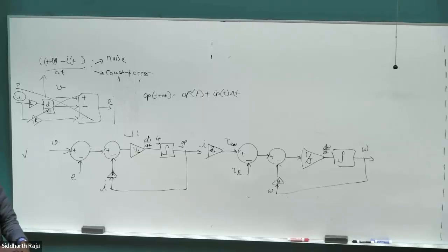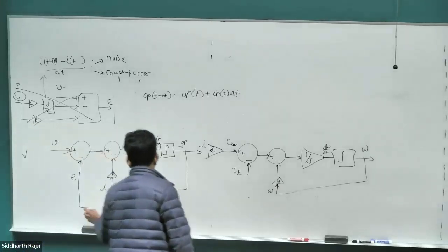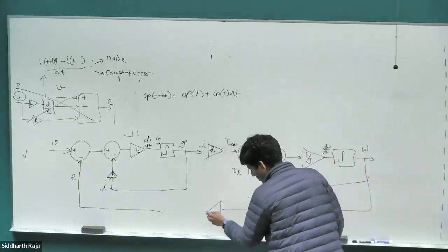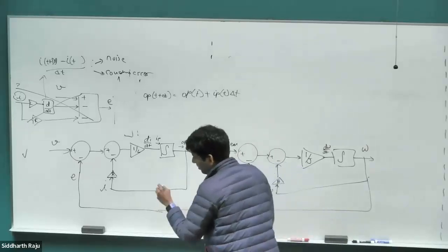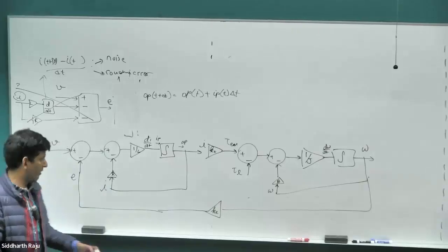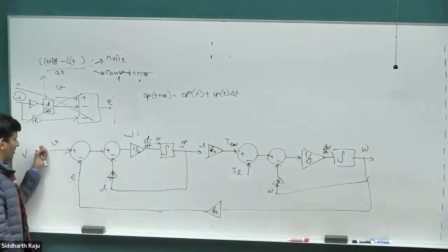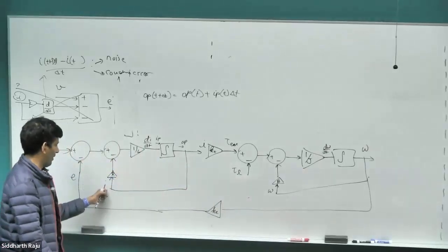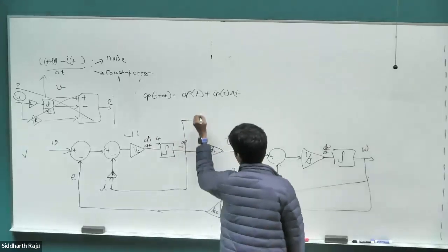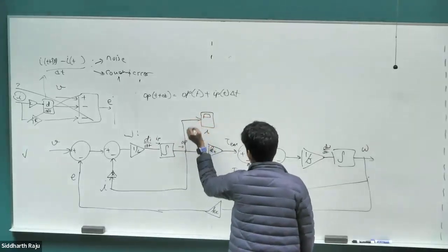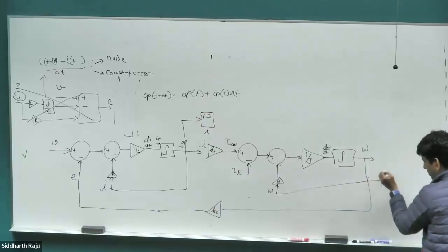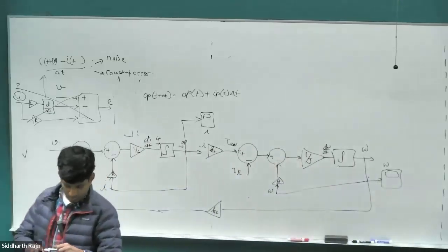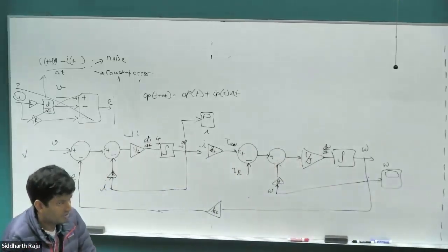It's only the E, right? Yeah. Okay, so once I have the speed times K is going to give me the back EMF, right? So you complete the full model. The voltage will be given, the load torque will be given, and then you implement this model, you can figure out what the current is. So you just put a scope here. And that will give you the current. You put a scope on this. That is going to give you speed omega. Right? Straightforward, simple system. Anybody any questions on how to model this?